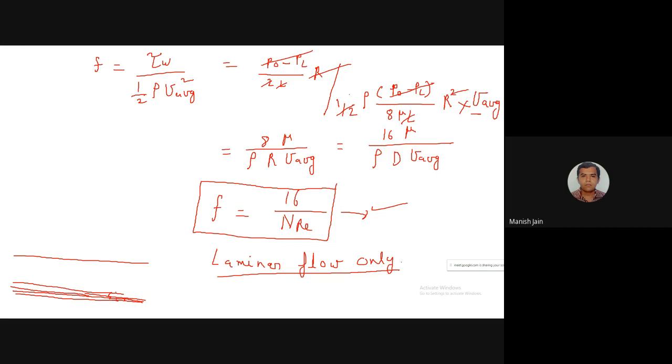So when you take the average, that surface roughness will not affect the flow, or it will affect the flow, but surface roughness will not affect the friction factor. And the friction factor is the basic property of the fluid only, in the laminar flow region. So how viscous is your fluid? What is the kinetic energy in your fluid? That is the V average. Or what is the diameter of the pipeline, or what is the density of the fluid? Those will affect the friction factor. Friction factor is not a function of the characteristic of the material of the tube, okay, in the laminar flow region.